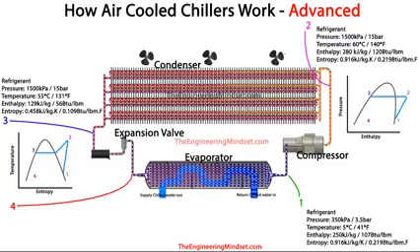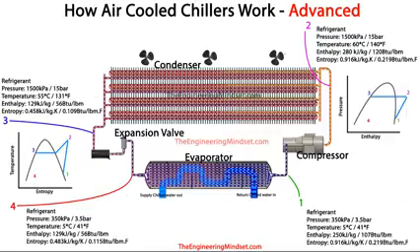Now point 4 we know is going to be somewhere within the vapor dome, so we can put our values just within there. And here we'll find that the refrigerant pressure has reduced down to 350 kPa or 3.5 bar. The temperature has also reduced down to 5 degrees Celsius or 41 degrees Fahrenheit. That's because it's expanded. The enthalpy has remained the same at 129 kilojoules per kilogram or 56 BTUs per pound.